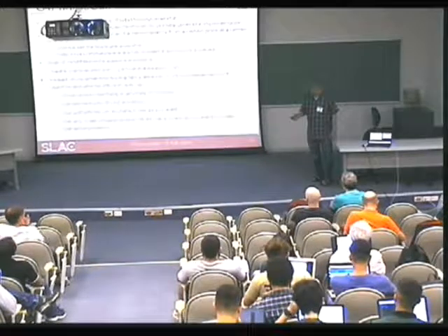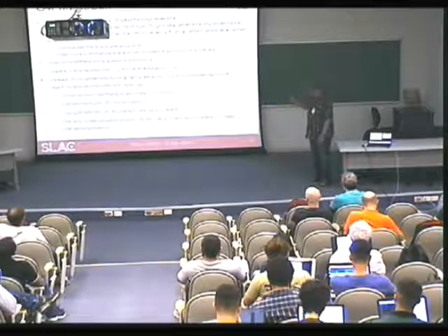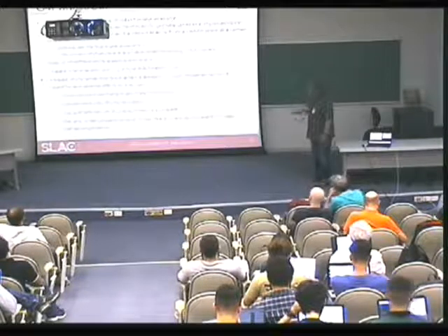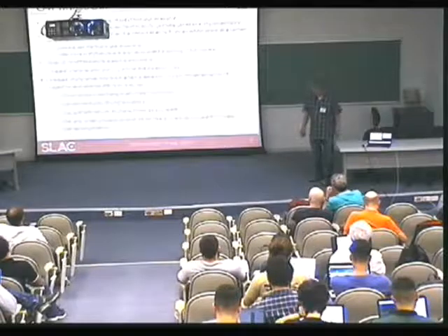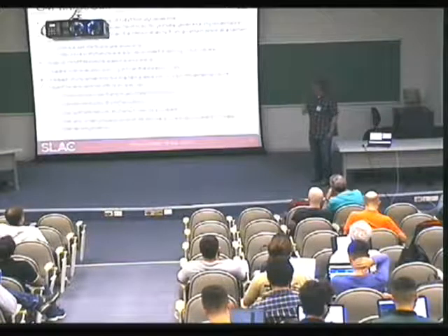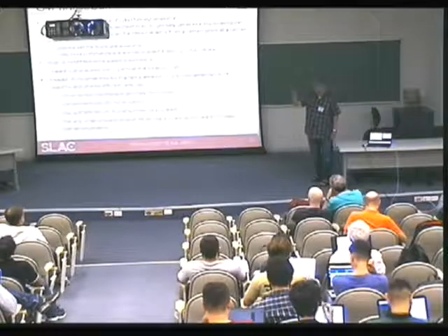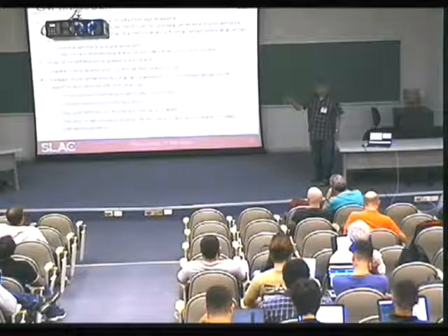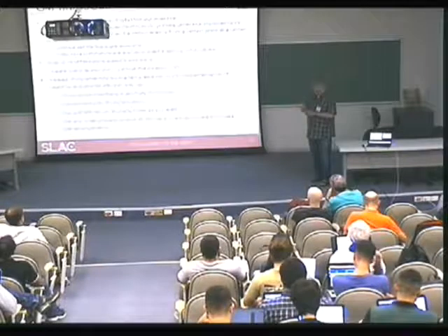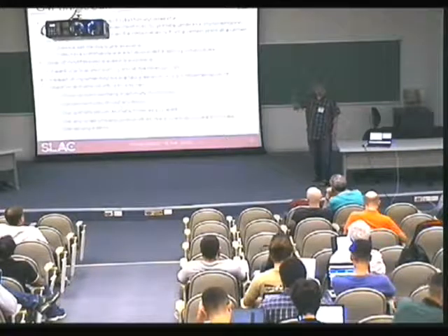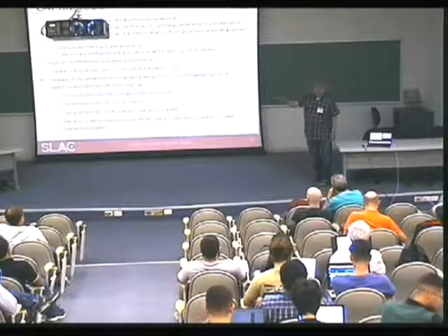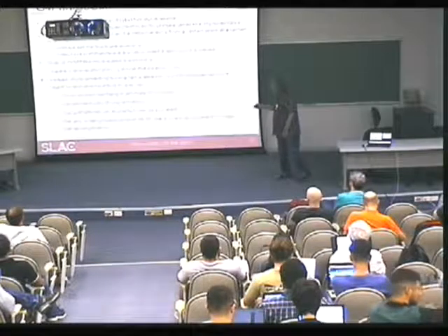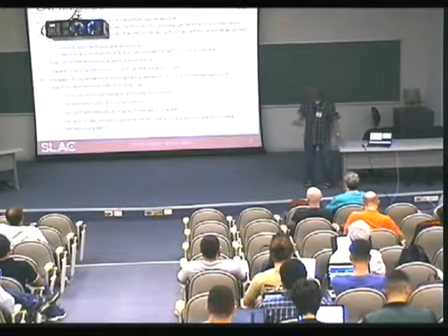You can employ the particle gun more than one time in your primary generator action. If you change the direction of each particle, that is a shotgun. And if you change the starting time of each particle, then that is a machine gun, right?